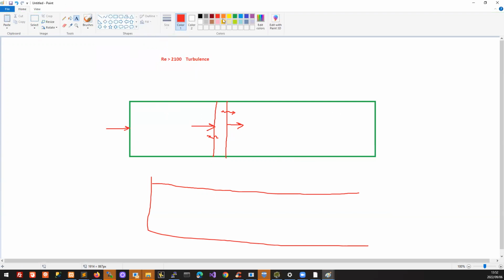And that is quite a crazy general statement to make. It's saying that if the Reynolds number, d u rho over mu, is quite large, then your flow is turbulent. So you have this kind of flat profile because it's in turbulent flow. Again, like we talked about the other day, if you have a tap and you have a high flow rate through your tap, then you get this turbulent flow coming through.